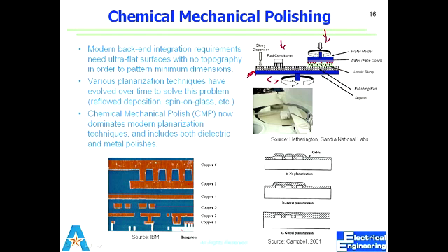There are some planarization processes which we call non-CMP planarization. A simple one is we spin on glass. So just like photoresist, we have liquid glass. Spin it on a wafer and heat it. What we are left with is a plain glass layer. That's called non-CMP planarization. Now, do you do that after you deposit things or before? Yeah, once you are done with your surface and you have made your contacts, and now you're ready to make vias, spin it, open your vias, and you have the next level of device fabrication on top of it.